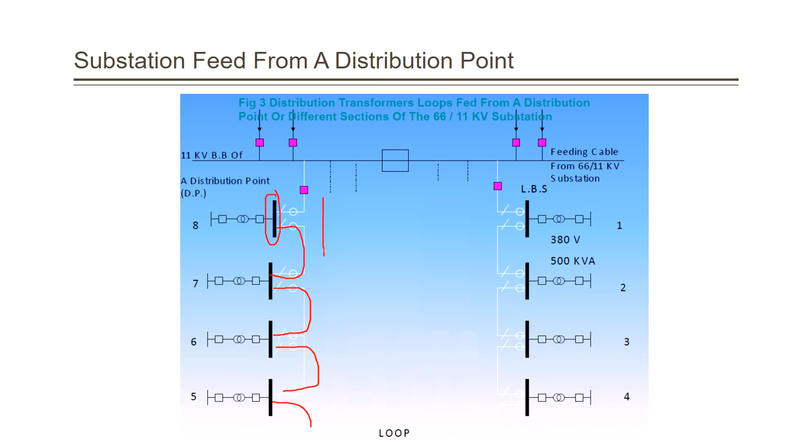So you will find that here, and connecting of course all of this here too, forming a loop. Okay, so you'll find that this one is connected to this one, and so on, and between them an isolating switch. All of this is forming a loop. This is what's called a ring main unit. But also to mention that you will find here that this one and this one are off. Why? In order to prevent the connection of this substation with this substation.